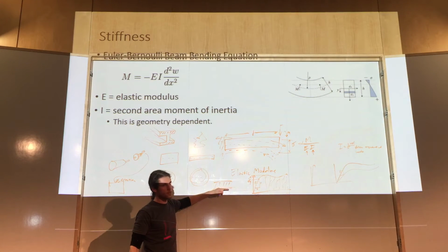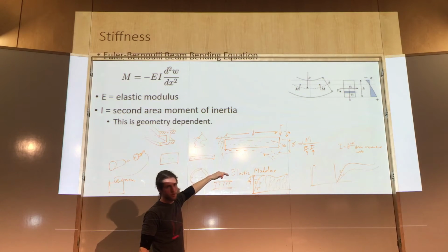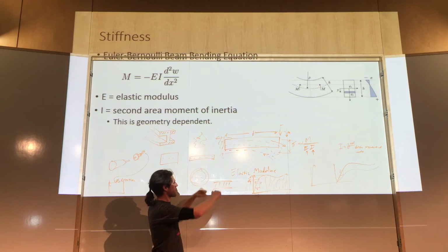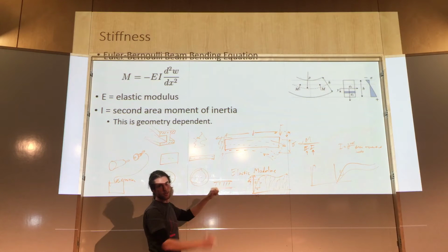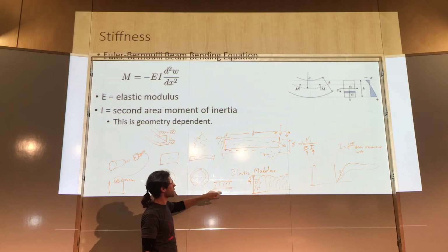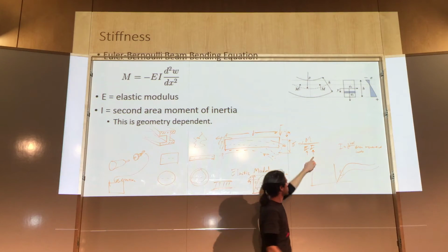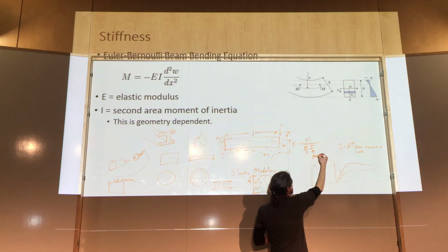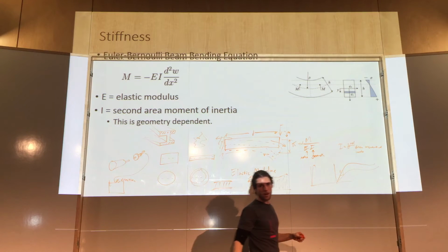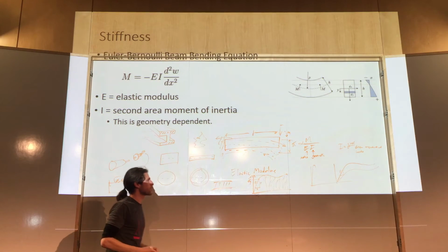The fiber is the thing that actually takes the load, right? And so you put them as far apart from each other as possible, so that they can actually resist that stress as much as possible. And so the combination of geometry and material combines to reduce your overall deflection. The higher you can make those numbers, the lower your deflection ends up becoming.